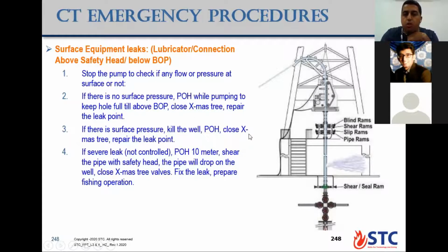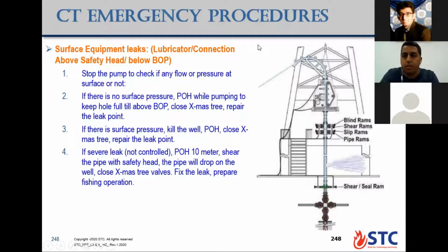Also, this is possible if the kill fluid is ready, because in most coiled tubing operations you usually have a spare tank with kill fluid ready. If you are working on a live well, a high pressure well, especially an exploration well, you must have volumes of kill fluid ready in case of emergency. This is also a recommendation or procedure. Yes, Mr. Khawar.